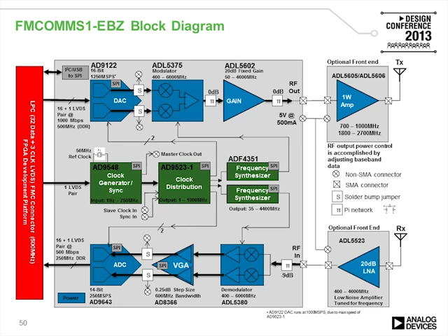So again, looking at our block diagram, we have a full transmit path with a 1.2 gigasample DAC, a 400 to 6 gig modulator, a 50 to 4 gig gain block, which kind of makes our transmit specs from 400 to 4 gig. And then on our receive side, we have our demodulator, our VGA, and our ADC.